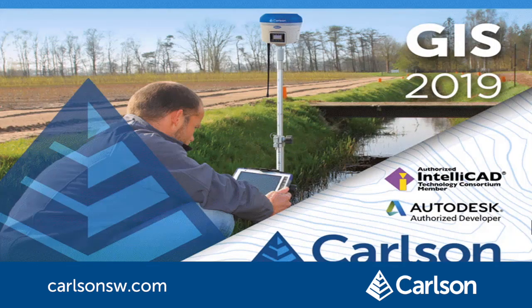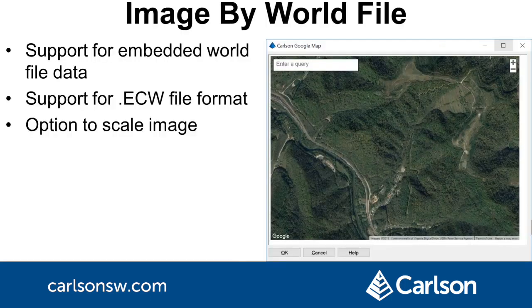Next is Carlson GIS. For drawing georeferenced image files, the program now supports image files with the positions stored inside the image file, instead of as a separate world file. Support for ECW files was added. There's a new option to scale the image in case the image units are different than the drawing units.